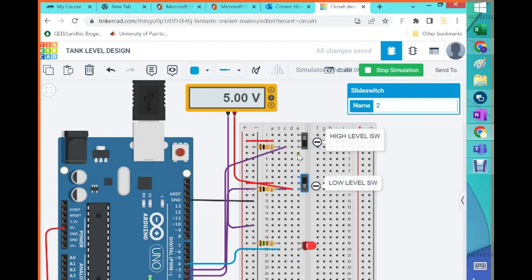Perfect. Now, this one should close because the water starts to rise until the last level switch closes. There we go. The pump should go to the off stage. Perfect. Now it's in the off stage. If this piece of code that we added fixed this, the next thing that's going to happen is that I start to use water from this vessel, and this guy will open. So let's open him up. There we go. The pump stays in the off stage.